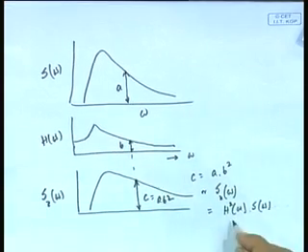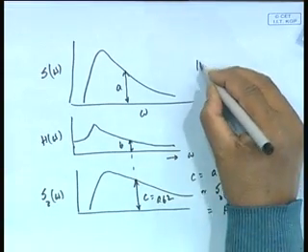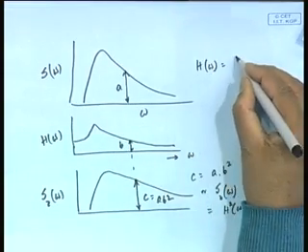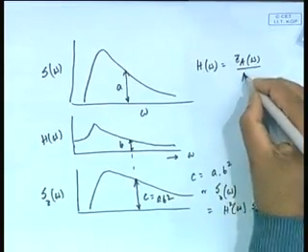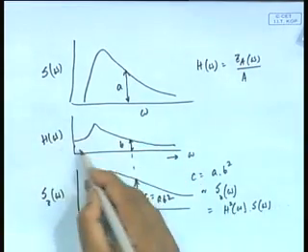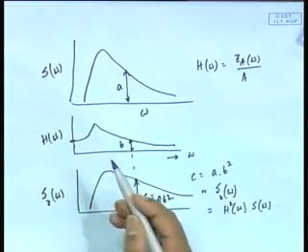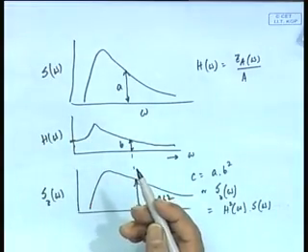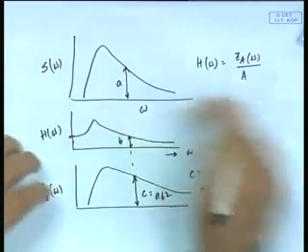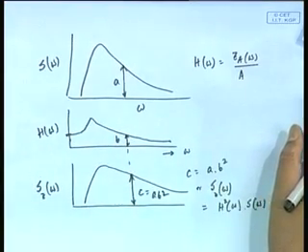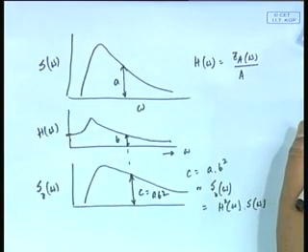Okay. So, what is H omega? H omega is the amplitude of response at that frequency divided by A, that is nothing but this, because you are plotting, see, remember here also we plot it. You can say it is a non-dimensional way of plotting it as if it is linear motion. Basically, you are plotting the output per unit input.